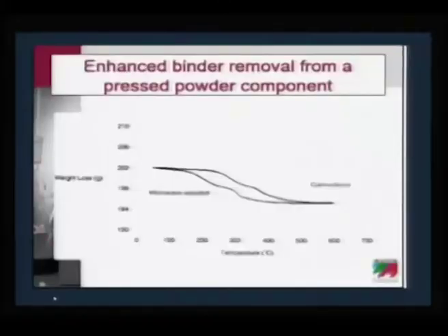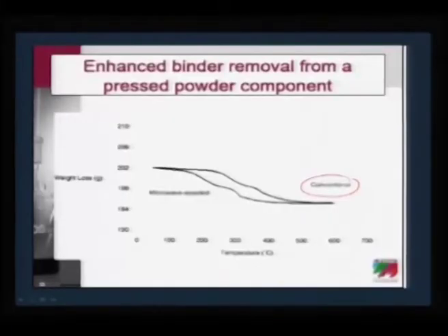And in sintering of ceramics, for example, one of the important problems that we encounter is taking the binder out of the matrix and then densifying it. As you would see here, in conventional synthesis, the binder is usually PVA, polyvinyl alcohol. Say 2% of polyvinyl alcohol is taken into a ceramic pellet like this, and it is heated to densify.